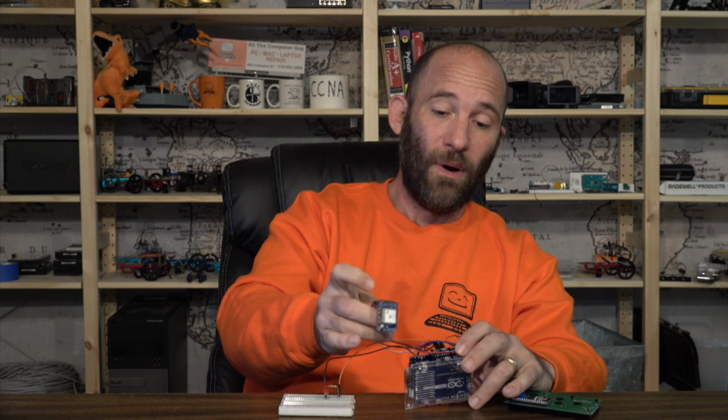Since we're using the Arduino Uno with Wi-Fi, that particular board requires that you use ICSP headers if you're going to be writing to an SD card. Whenever you're dealing with an SD data logging module or shield, different boards interact with that shield in different ways. The Arduino Uno with Wi-Fi requires the ICSP headers in order to communicate with the shield. The previous data logging shield that I've used in other classes, for things like the Arducam, which I actually like, simply doesn't have ICSP headers. The shield I have that allows for an SD card and has ICSP headers happens to be the Ethernet shield. So that's why we're using the Ethernet shield.